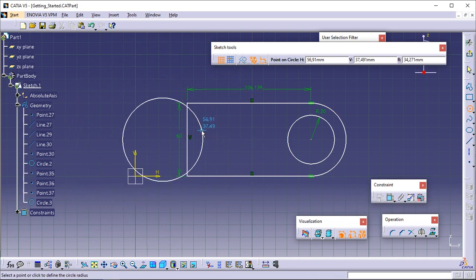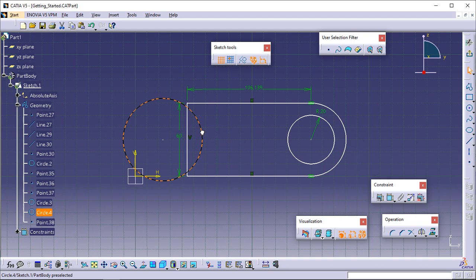Note that when the SMARTPICK cursor crosses a fictitious horizontal line that would go through a point, SMARTPICK snaps in order to remain horizontal to this point. In this case, no constraint is created. The circle is created as shown.